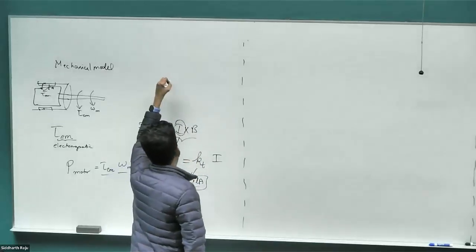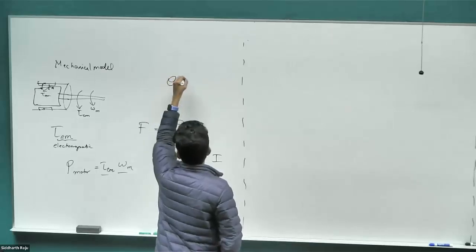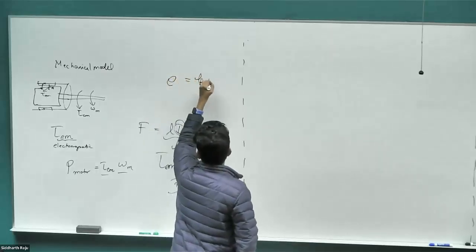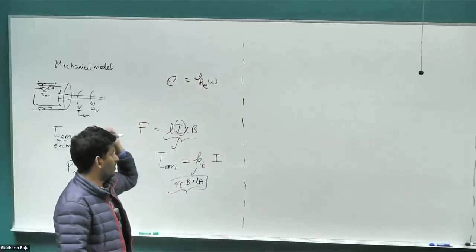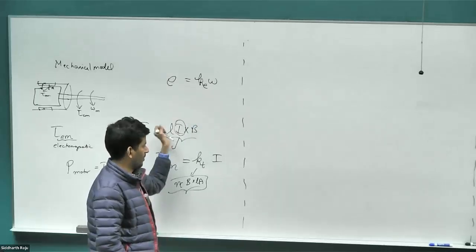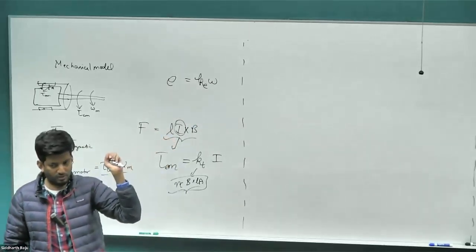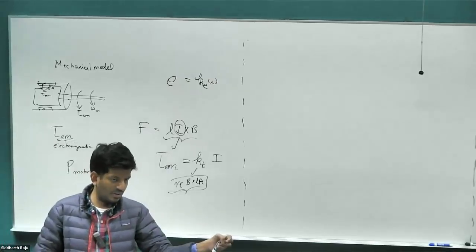The thing that was proportional to the voltage, the back EMF, so the speed is proportional to the back EMF, right? So if you adjust the terminal voltage, in effect, you're adjusting the speed of the motor for the most part, ignoring the losses, drops in the resistor and inductor. That's what we did in the second class in a hardware demo, right?